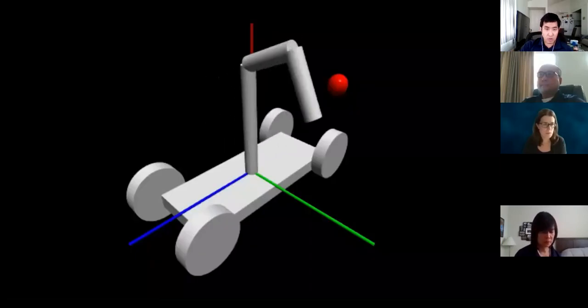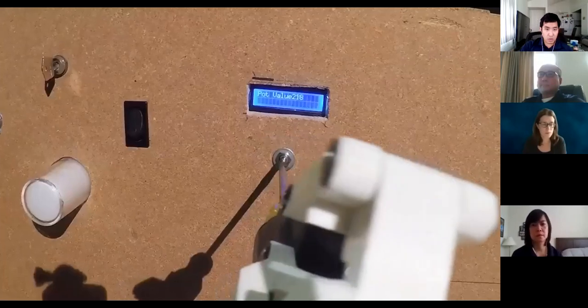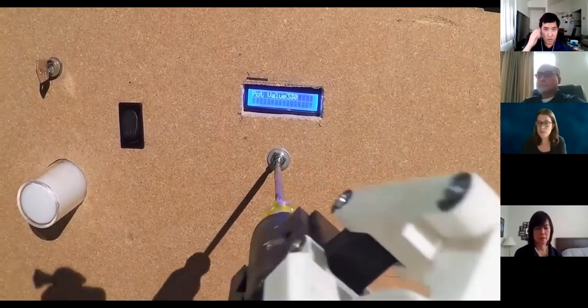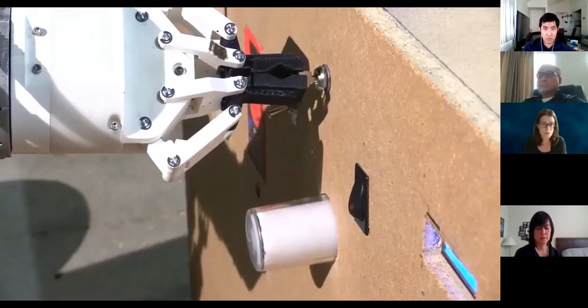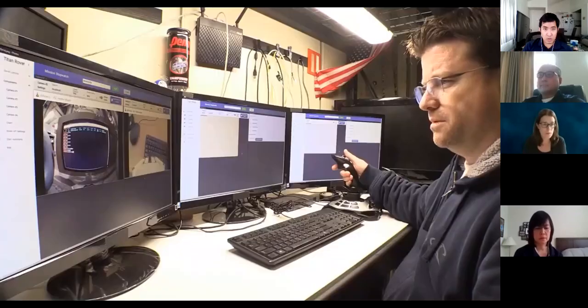Feedback is designed into every joint of the robotic arm to enable real-time position of the arm and allow the use of inverse kinematics. The gripper can accommodate a vast array of objects using specialized gripper tips to maximize the points of contact on many standard and oddly shaped objects. The gripper can be field swapped for other types of end effectors if needed.